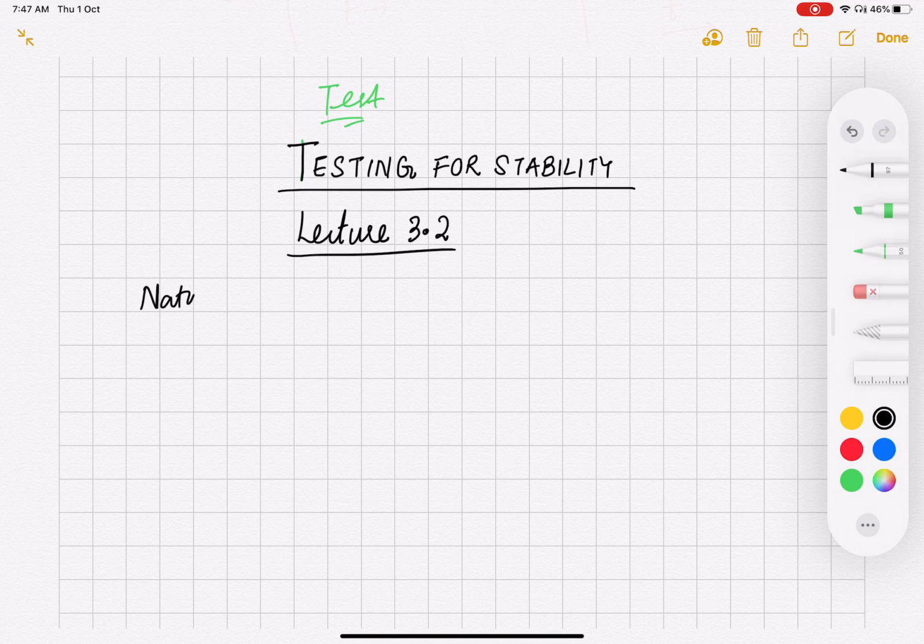And suppose both the poles are in the right half plane, then you have s square minus 5s plus 6. Again, one of the coefficients of the characteristic polynomial becomes negative.